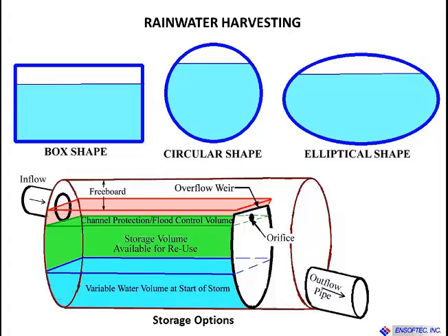The runoff reduction depends upon the type of use of the stored runoff. The runoff reduction credit can be applied by the user after approval by the agency. Credits up to a maximum of 90% can be taken if all 1 inch or less storm runoff is held in these facilities and is used through demand. The storage facilities should be sized such that no overflow occurs for these floods. There are programs and spreadsheets to enable computation of this credit.